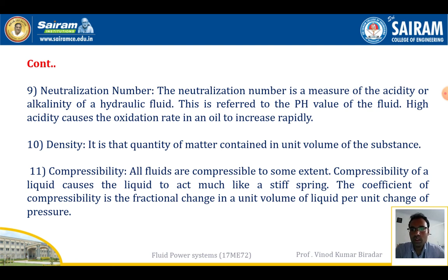Next one is compressibility. All fluids are compressible to some extent so that the fluid can flow smoothly. Compressibility of a liquid causes the liquid to act much like a stiff spring. The coefficient of compressibility is the fractional change in a unit volume of a liquid per unit change of pressure. All these terms we will understand better with the help of solving problems.